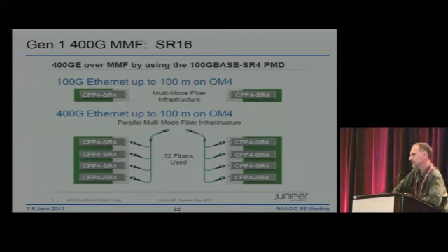Here's a diagram I borrowed from my friends at Juniper. It shows you how you'll be able to get a 400G link just by combining the output of 4 100G modules, again, using an octopus cable, this time in exactly the reverse way as you do for multi-link modules. Here you take 4 links and combine them into a single by 16 MPO link. So you can actually then have a card where you have either N by 4 times 100G ports or N by 400G ports.